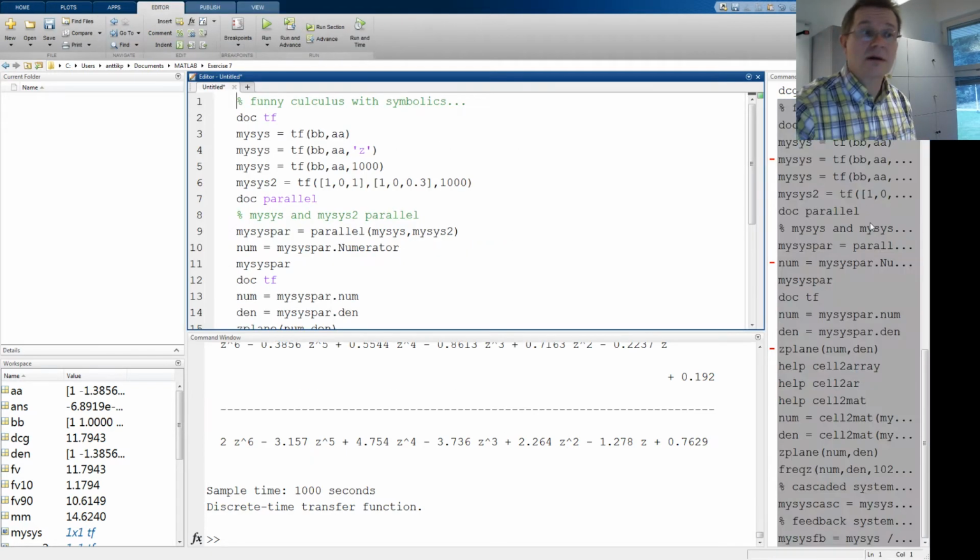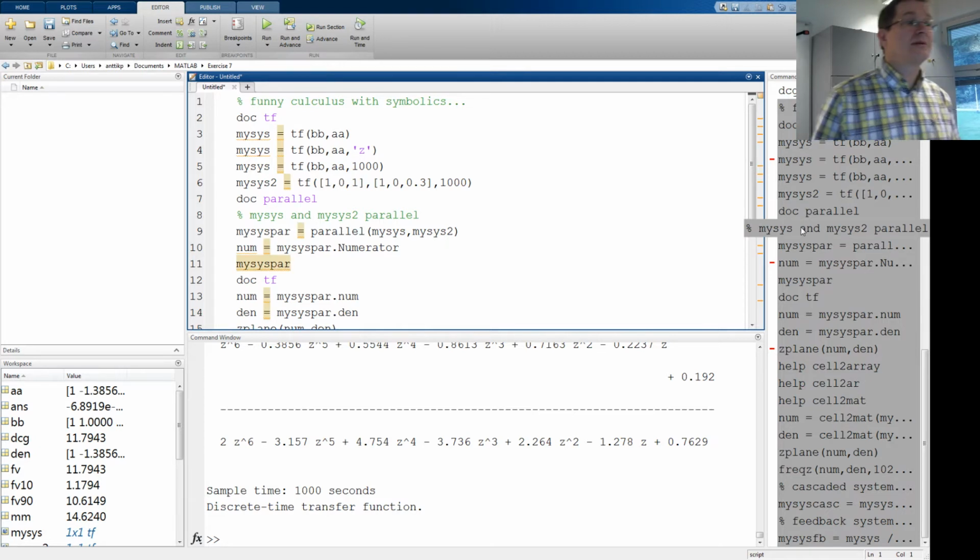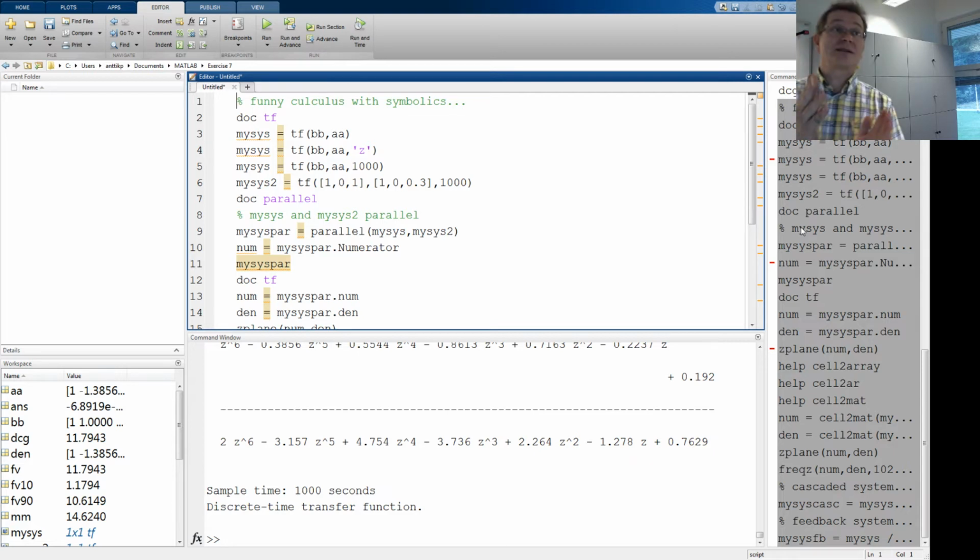Then create a script, and there start fiddling with these KD, KI, and KP values, one at a time. See how they actually affect the step response.